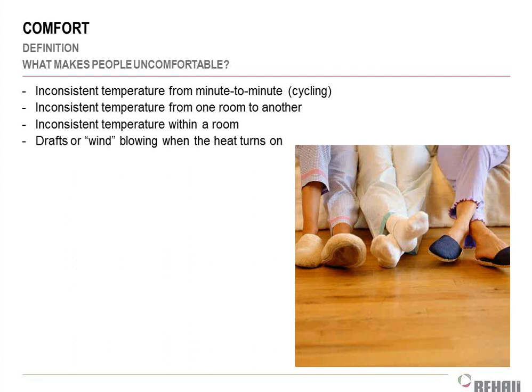In terms of airflow, in the summertime, you kind of like the diffuser airflow blowing on you. It helps cool you off a little bit, takes the heat away from your body. In the wintertime, it's the opposite. You pretty much want no air blowing across your body. You'd prefer not to have an air-based heating delivery system if possible, because it's going to give you a cooling effect with the evaporative effect of your skin, not to mention the convective effect. So you don't want that to happen. You'd rather have a system that does not move air at all for the heating season, if possible. Now, obviously, you still have ventilation concerns and things like that, so you're going to have some airflow, but minimal is best in terms of heating.